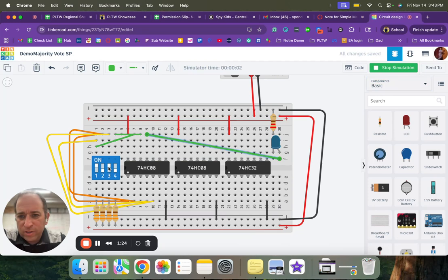And you'll notice the light is off right now. All of the switches are off. And we programmed this to be the president and the treasurer. So whenever I do that, it should be off. And 1 and 4, or president and treasurer, it should be on. Now, the other ones don't matter, but we have an AND gate. So this says this 1 and 4 have to be on to work. Okay, that works.